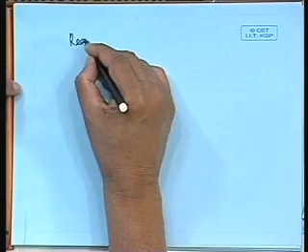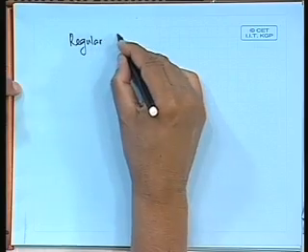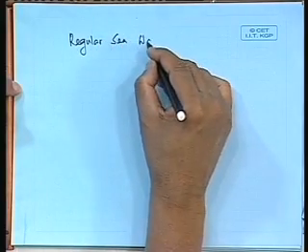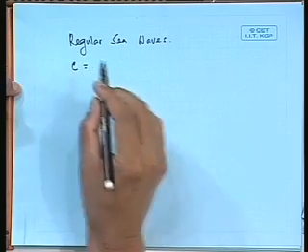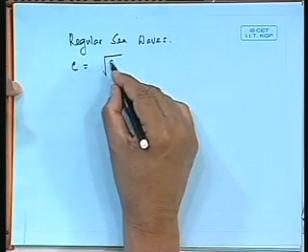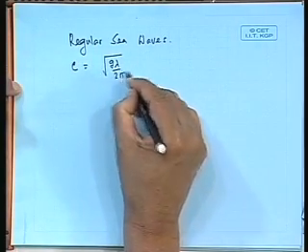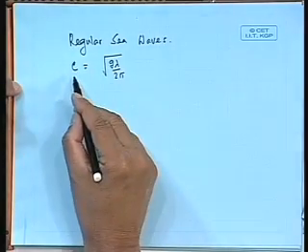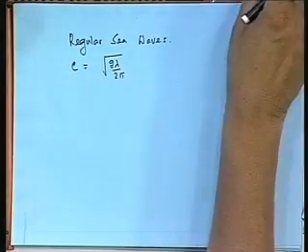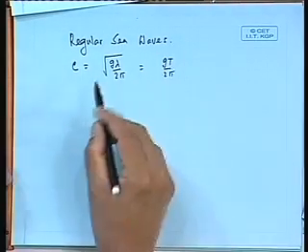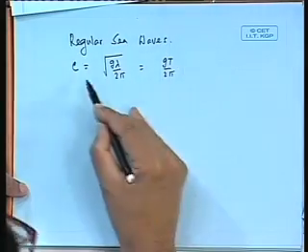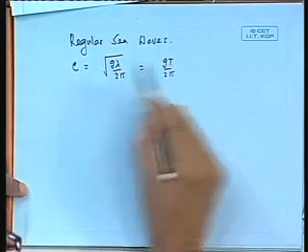Okay, we will continue our discussion on regular sea waves. We ended up at this relation, g lambda by 2 pi, that is, or we can also say it is g T by 2 pi, to say that longer waves travel faster and also waves with higher period travel faster.